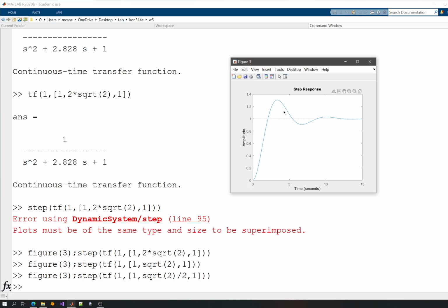So Ziegler-Nichols doesn't actually provide you with a solution that should be used, but they claim that this method can be used for any system with a black box approach. So you don't have to know the model of the system. You just go ahead and try to bring the system to oscillation, and then you note 2 values about that. One is the gain that you've used to bring it to oscillation, and the other one is the oscillation frequency, and you use the time constant of that frequency, and then you can just come up with PID parameters.